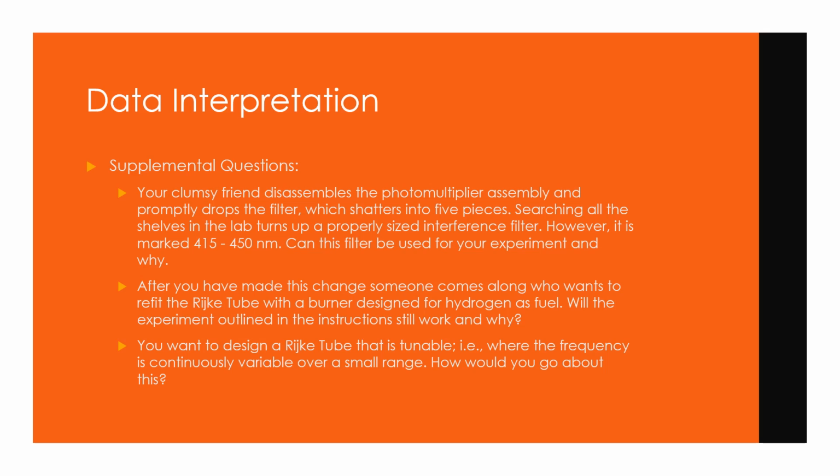The answer to the first question is yes. Although this interference filter detects light with much longer wavelength than the light produced by the combustion of OH in the Rijke tube, which is what is being detected by the filter in our experiment to characterize reaction rate, other free radicals are produced by the flame in the Rijke tube that fall within this new wavelength range. Alternatively, if no reacting free radicals produce light in the filter's range, current would not be generated.